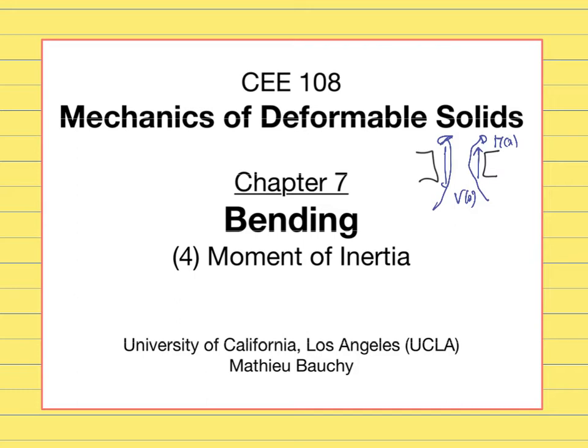And then we saw different methods. We saw that we can calculate those internal shear and internal moment by using the method of sections. We saw that a more convenient method is usually the integration method. And we also saw the graphical method that allows us to not analytically calculate the internal shear and the internal moment, but to get the trend of how the internal shear and internal moment depend on x along a given beam, and where the moment is maximum.